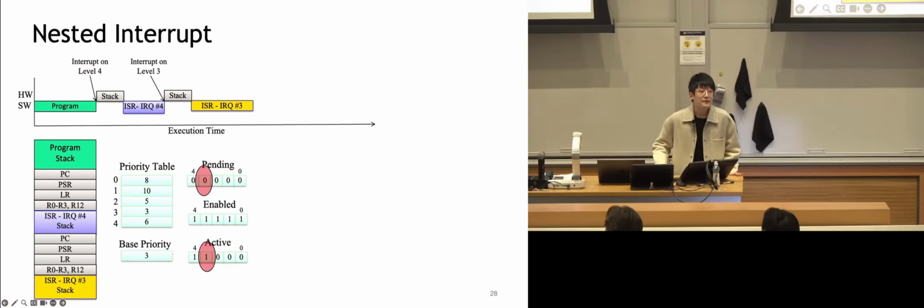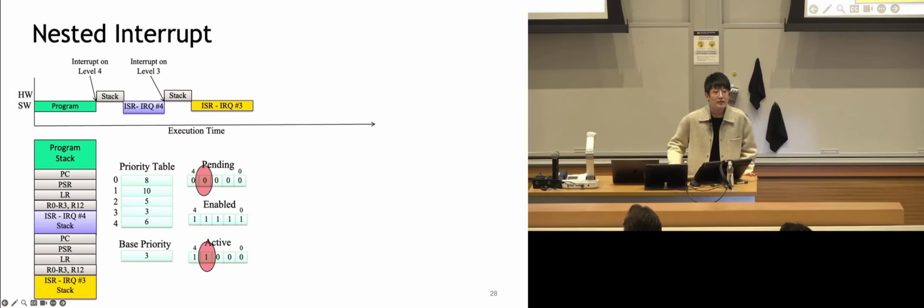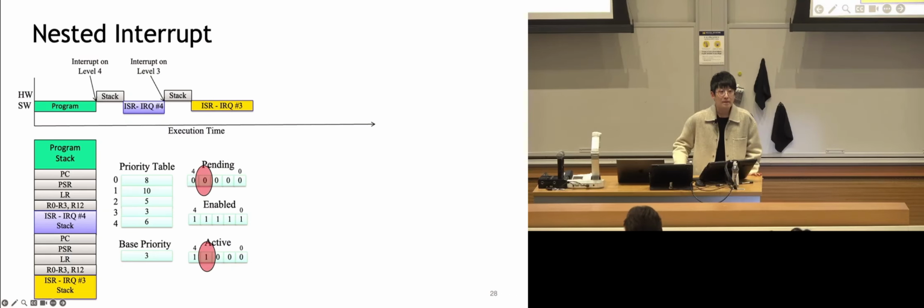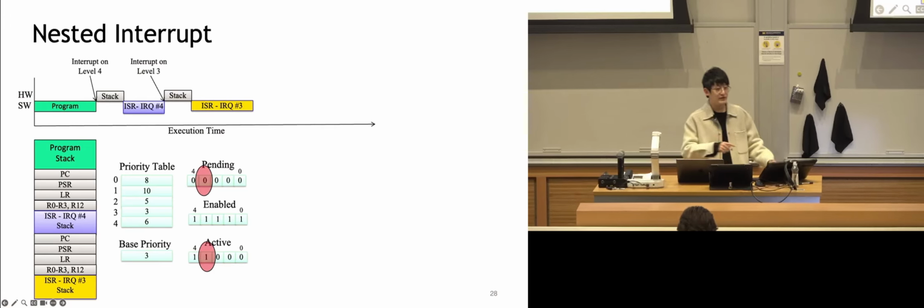So what happens if a higher priority interrupt becomes pending during stacking or during unstacking? Will the stacking or unstacking complete before the preemption occurs, or will it be interrupted itself? Great question. So we have one case for that. Actually, it's the late arrival.